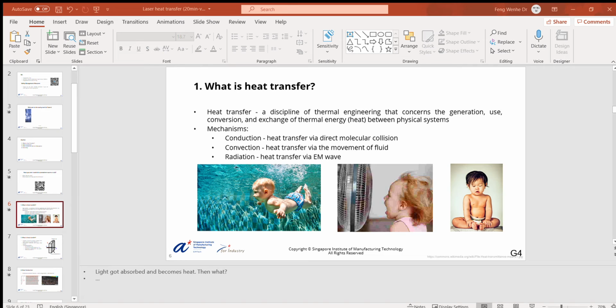But this is already so much deeper than the optical penetration depth, less than 100 micron, because aluminum is normally considered an opaque material. It doesn't transmit light. And also, our laser spot size is only between 10 micron to 10 mm, which means the heating can be quite localized, and this is the base of micromachining.